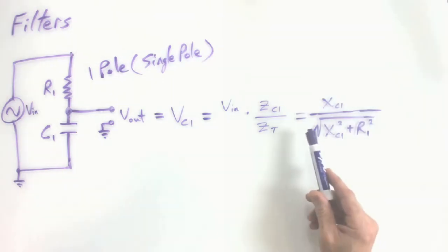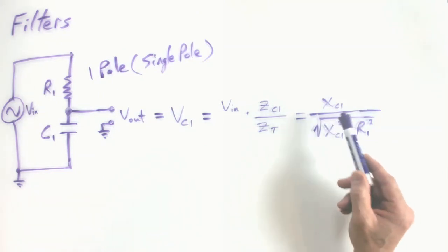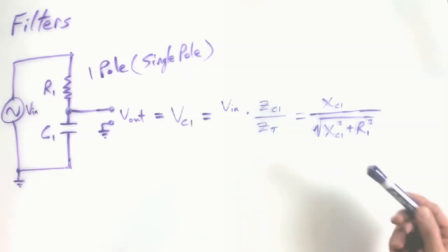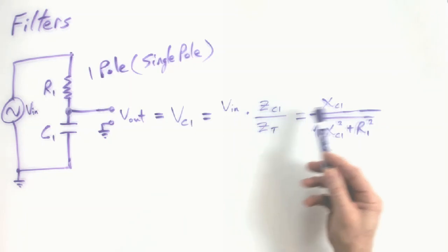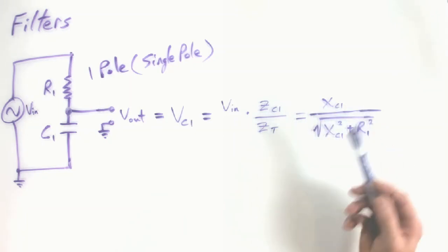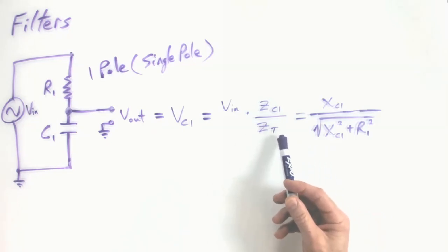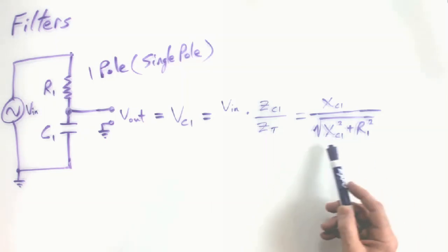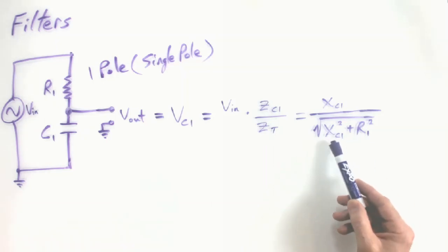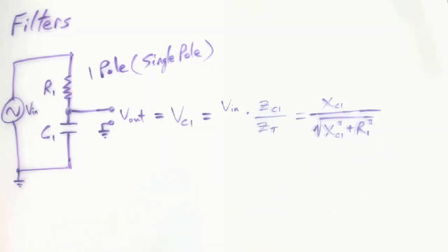Also, if you remember from the AC course, the impedance of a capacitor is very close to the same thing as the reactance, provided the equivalent series resistance of the cap is low. So that's a fair estimate to make. So that would be the reactance of C1. And then the impedance of the voltage divider, the circuit as a whole, is of course the Pythagorean theorem here, where we have to geometrically add reactance and resistance. So there's that to get the total impedance.